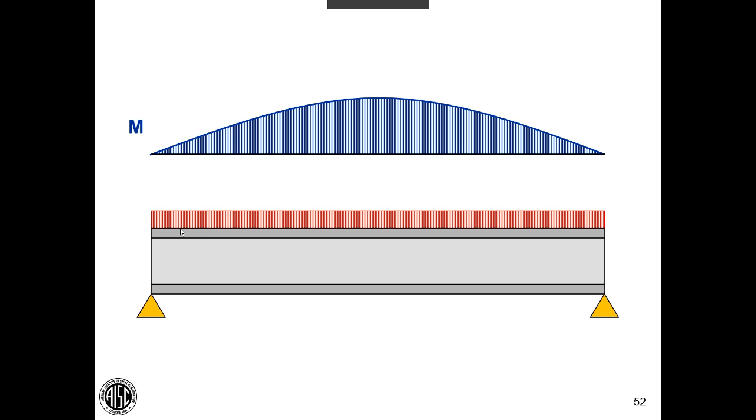So our objective is to make welds as long as we can and of the smallest size. I quickly add the caveat on size. We never want the size to be smaller than the minimum pre-qualified size that we have listed in AISC Chapter J, and I think it might be Table 2.1. But we don't want to be smaller than the minimum size. Otherwise, we make it long and small for economy.